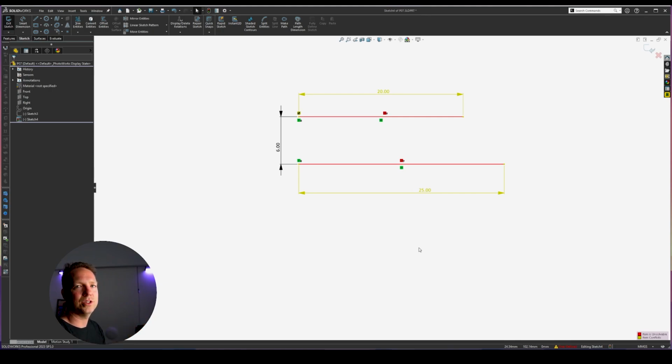So building up the relations and dimensions. And to do that, you simply select what's red. Now I'm not selecting the line, I'm just selecting the relation. And I'm going to hit delete on my keyboard. And once I've deleted that, the sketch is no longer over-defined because these two are able to solve. All right. Now, those lines no longer need to be equal, which means the dimensions can be calculated, the lines can be made to those lengths, and it works.